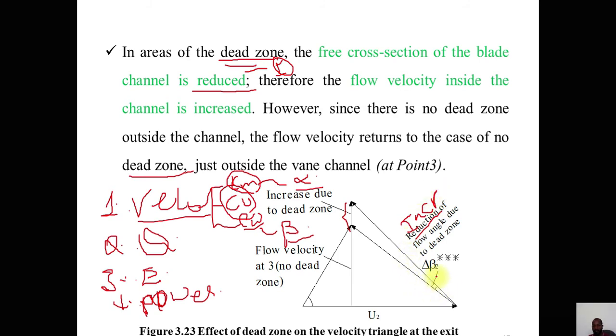Since there is an increase in the blade angle of inclinations, there is an increment in relative circulation and the flow velocity. In case of relative circulations, only the relative circulation is increased, but there is a decrement in flow velocity, which is the tangential velocity actually.